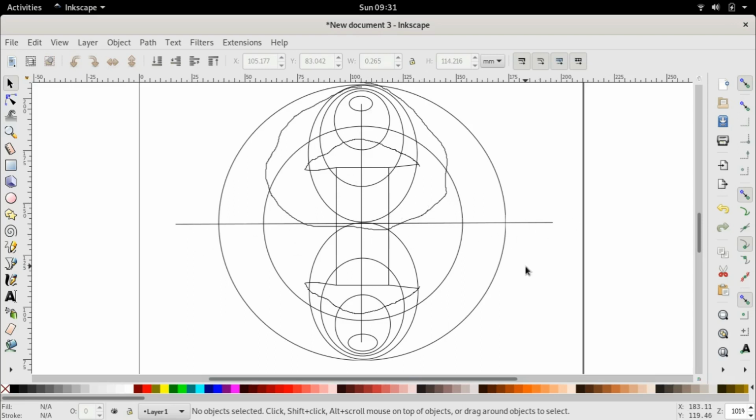Now the rotor position is theta equal to 90 degrees, or pi by 2, however you wish to say it. In this case, the flux lines are totally different. The reason is because now the air gap is huge in this center. The air gap is the least only in this region. So the problem is that the flux cannot flow. Only a few flux paths can actually flow through this pole.